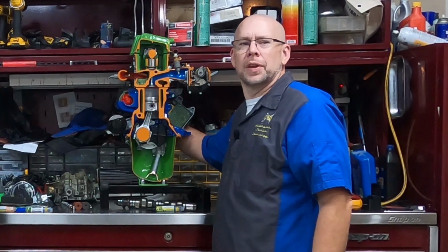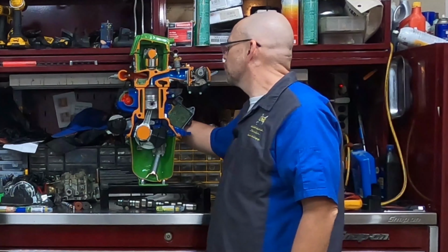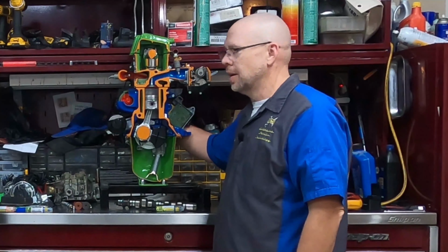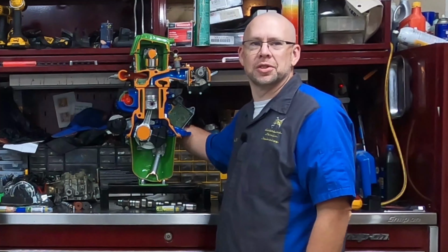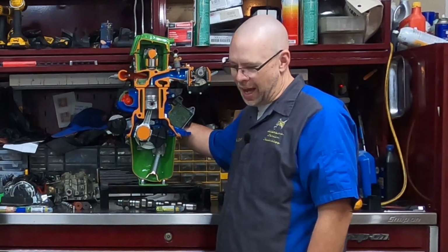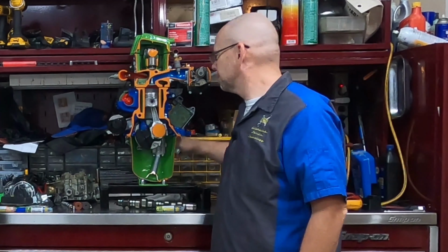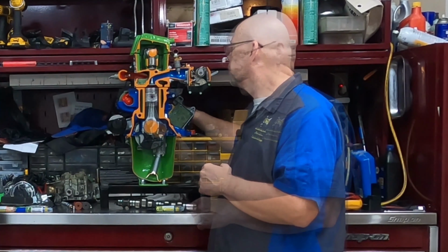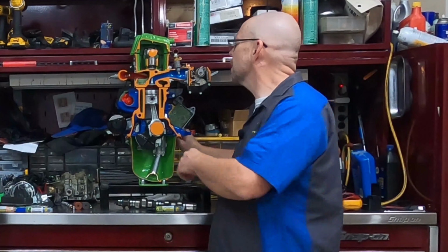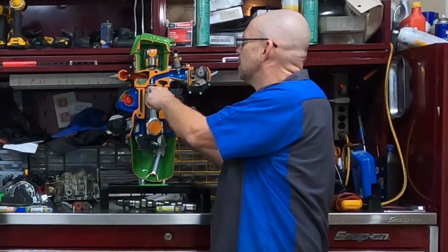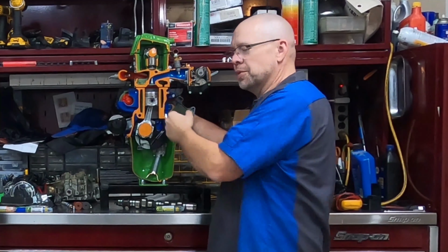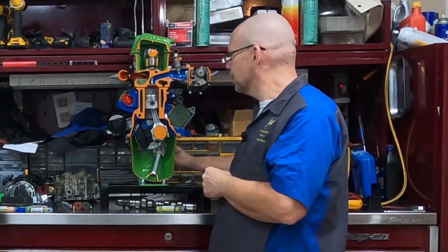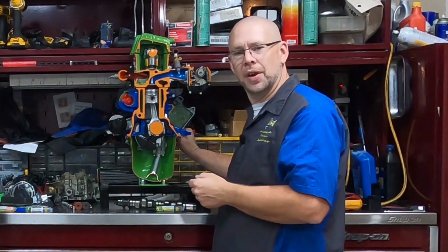Now, where things change. On a stationary engine that runs at a single RPM, we could keep that constant. But we're talking about automotive applications, and these are not stationary engines, and they vary a lot. If we speed up the engine, we have to change the timing because things happen faster. When we speed this engine up, if we were firing this at close to top dead center and then by 10 degrees it was all supposed to be burnt out, well, that's a far cry in time at 800 RPM as it is at 5,000 RPM.